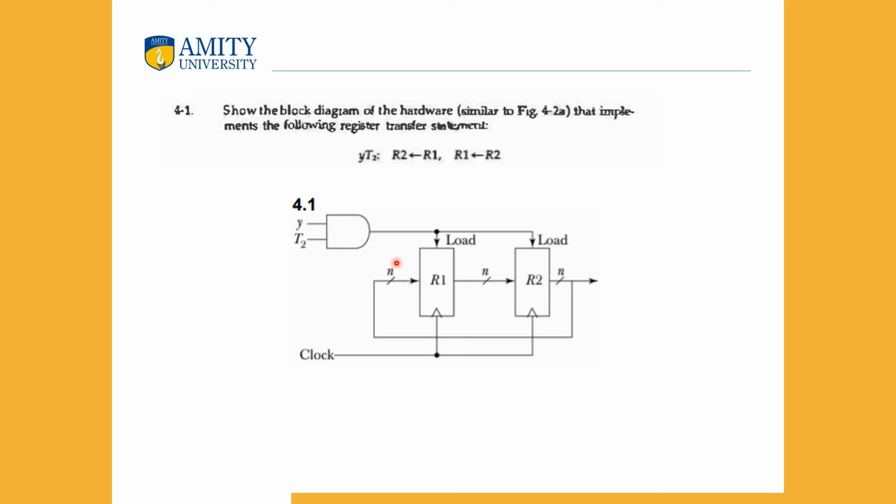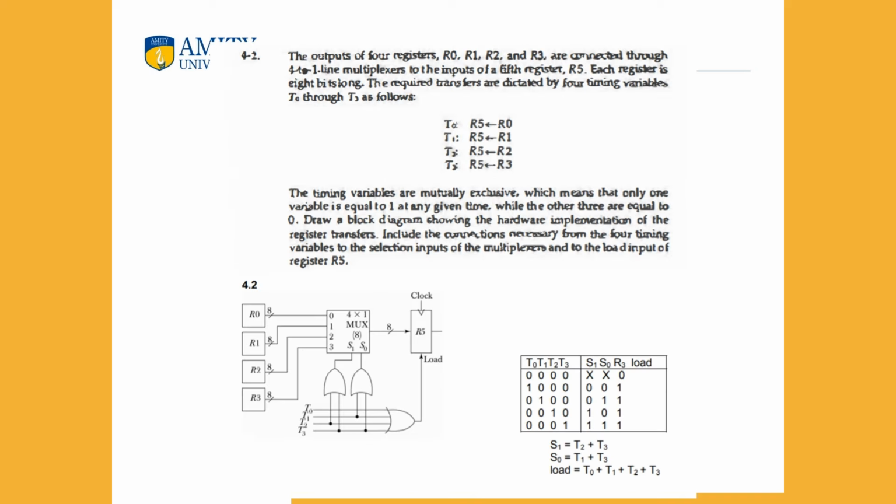Fine, this is also n bits, and both the conditions can be carried out, R1 stored in R2 and R2 goes to R1. We do need to remember to add a clock to it because both the instructions are being carried out at the same time at a given condition, hence the clock cycle has to be added to it to show the clock transition, a single clock transition for carrying out both the tasks.